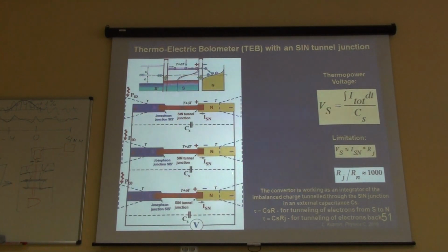So we have a parallel connection of many bolometers. All of them are without bias. We only collect voltage, and we are waiting. They are quiet, zero bias, no noise, nothing is happening. And then if a photon is coming, it would create a very effectively high impulse here. That means it's a jump to h omega, heating, and then we will collect some voltage due to tunneling of these electrons and holes. The way back is through leakage resistance.